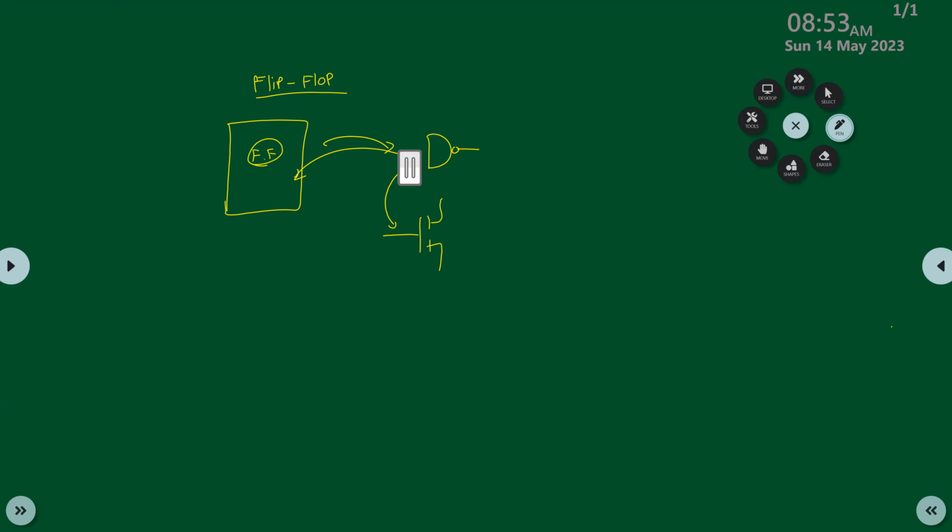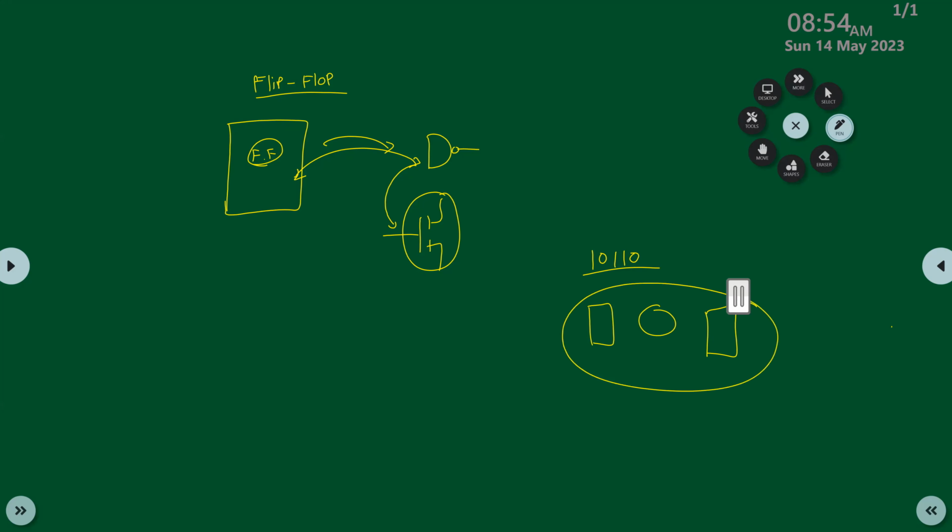But it is not easy to design CMOS gates every time you write code. Let's say you are writing code for a bigger finite state machine, detecting the 10110 pattern. In the state machine, you have flops and combinational logic. Designing all this using the raw approach is very difficult, because each flip-flop has 4 NAND gates, and the combinational part also has AND, XOR, XNOR, and every other gate. Designing all these logic gates every time with CMOS logic is very difficult.